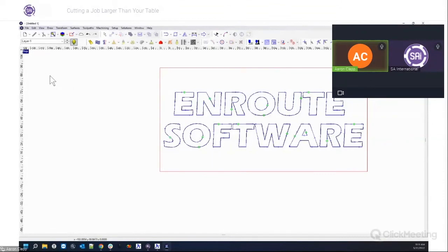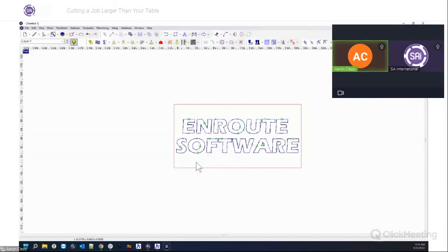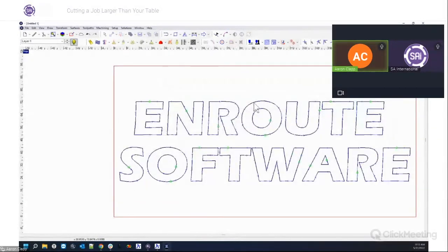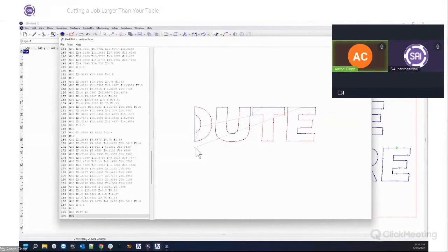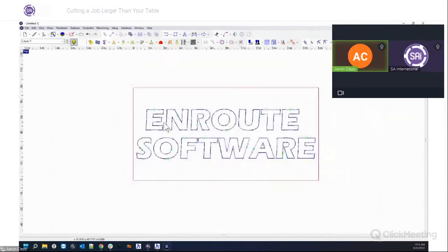Yeah, Bill, I'd say leave it alone. Right. It becomes too complicated. You could probably mess around with it, and here's what you could do if you really want to see how it affects your machine specifically, because your driver is also going to have a slight effect on some of that. And so yours might not look exactly like our typical example here. Like I said, your origin could be shifted up here or up here based on your driver. So maybe a good test would be you can use backplot to actually verify what some of that stuff does.